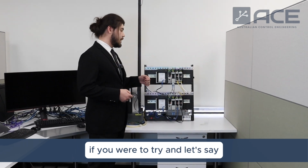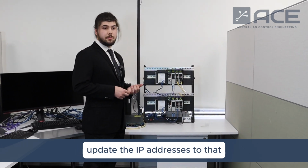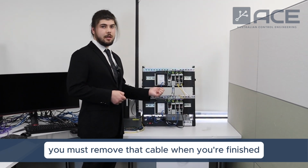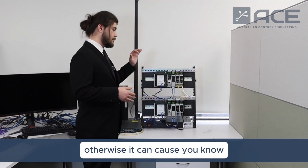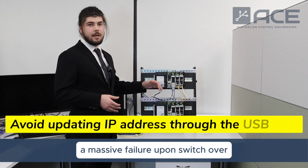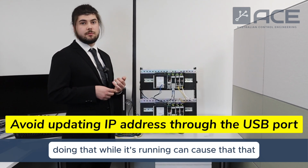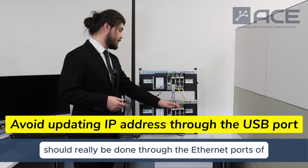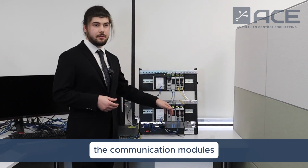If you were to try and, let's say, update the IP addresses through that USB port as it's being used, you must remove that cable when you're finished. Otherwise, it can cause a massive failure upon switchover. And even doing that while it's running can cause that event, so that's something to avoid. Everything should really be done through the Ethernet ports of the communication modules.